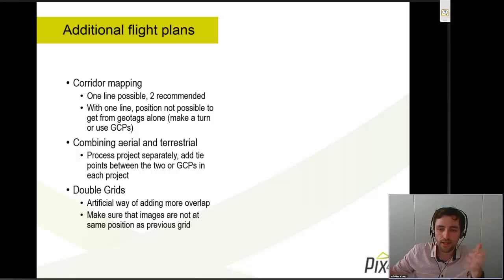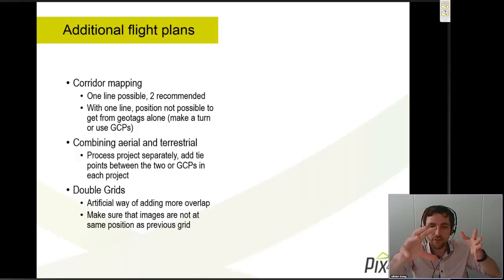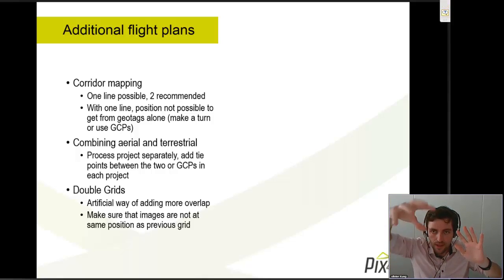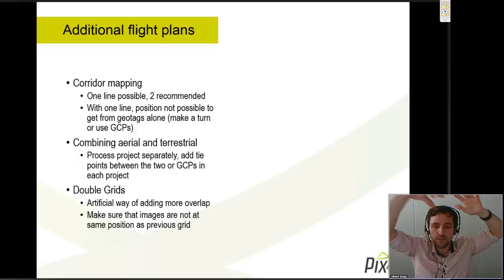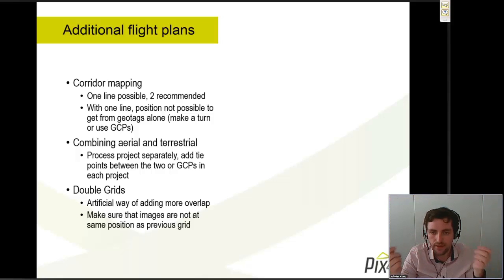The first way is that you need a very smooth transition between your ground imagery and your aerial imagery. Let's say you have a copter, you can start by taking the facade of a building, but very importantly, after the oblique facade, you need to take a lot of imagery between this oblique and a flight plan which is more nadir, and then you can fly a grid. If you do that nicely, you can add everything in a single project and the software will process it alone.